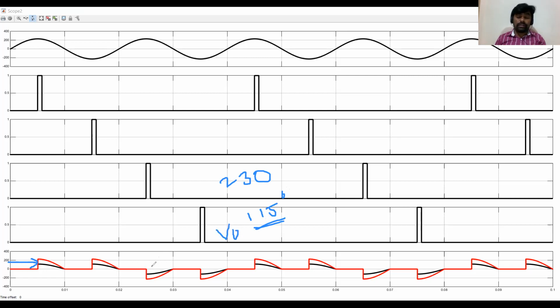And if you see, the frequency is 25 Hz, because this is completing one cycle here, which is for 20 millisecond. During 20 millisecond, we are getting only the positive half cycle, and for the remaining 20 millisecond, I am getting the negative half cycle, which means the output is completing one cycle in 0.04 second. So 1 by 0.04 second will give 25 Hz.